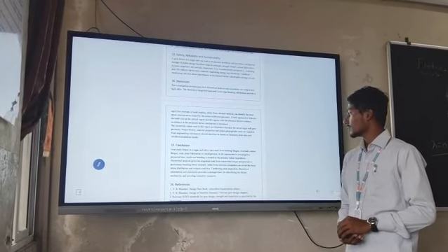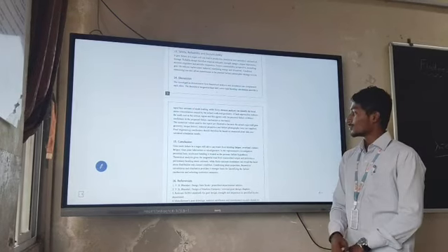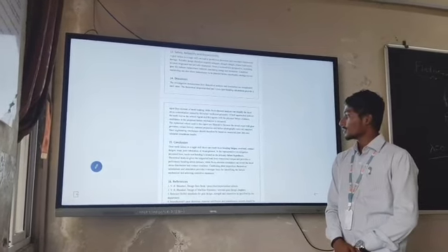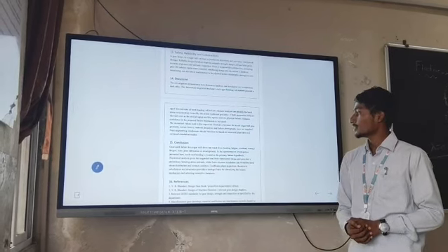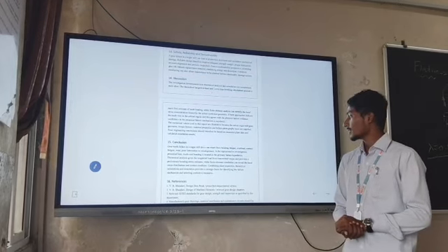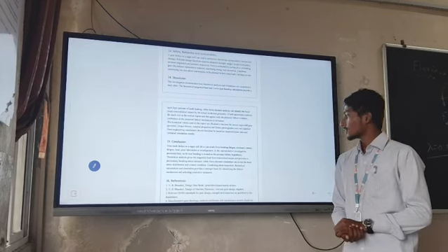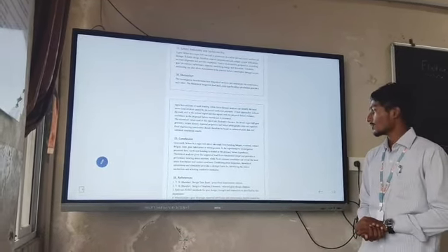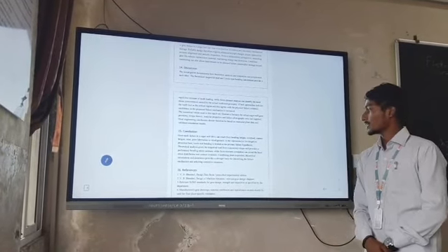In the representative investigation presented here, tooth root bending is treated as the primary failure hypothesis. Theoretical analysis gives the tangential load from transmitted torque and provides a preliminary bending stress estimate, while finite element simulation can reveal the local stress distribution and contact condition. Combining flank inspection, theoretical calculation, and simulation provides a stronger basis for identifying the failure mechanism and selecting corrective measures.